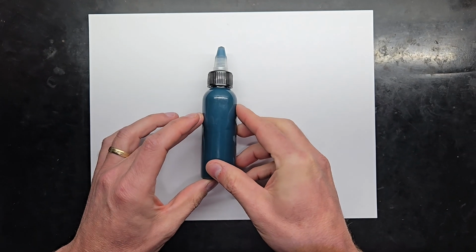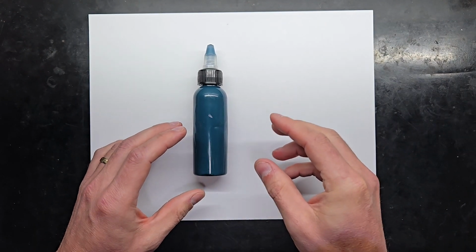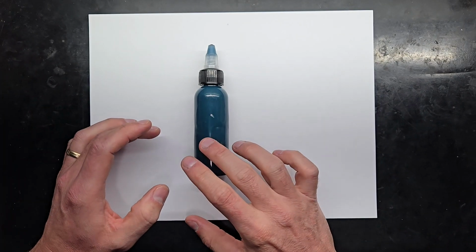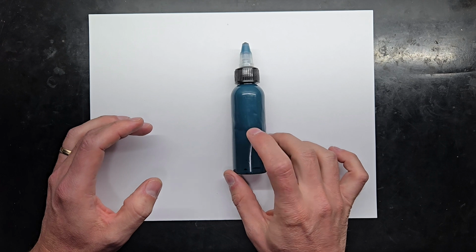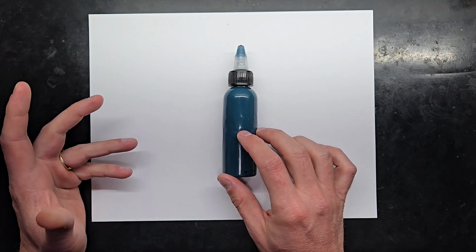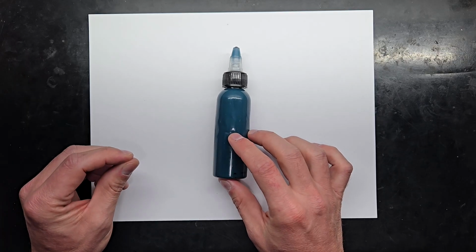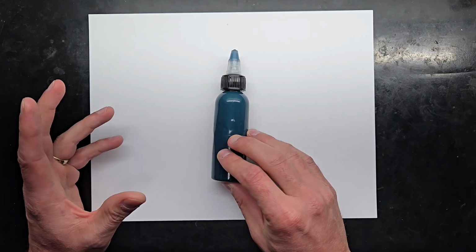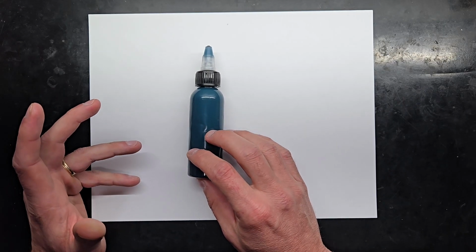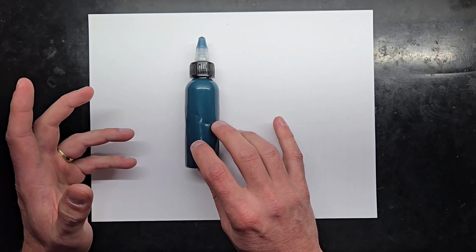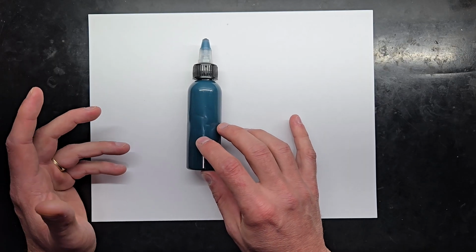So the non-Newtonian aspect of grease, and again, you can formulate it to get the different properties that you want, but that's one of the reasons that it makes it a little more difficult to understand for most people, because it doesn't always behave the way you think it's going to. And so again, that non-Newtonian aspect can be quantified through the rheology measurements of the grease.